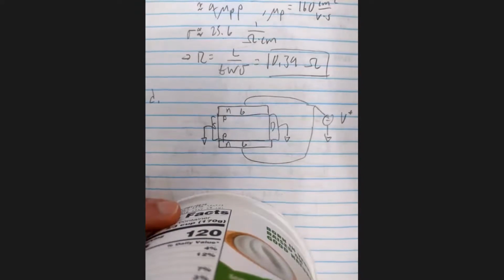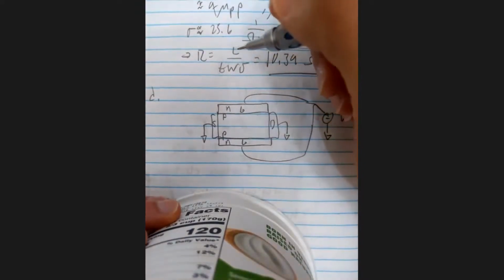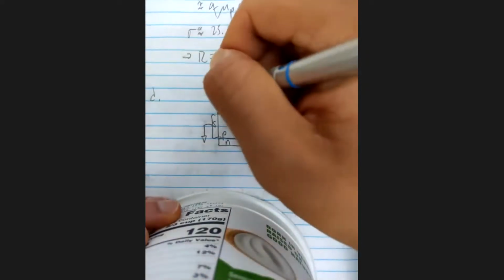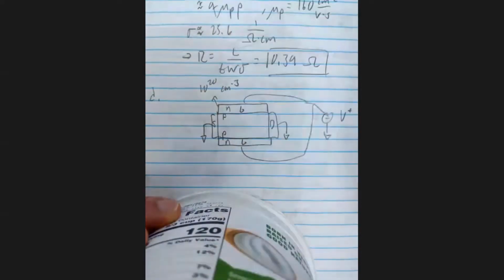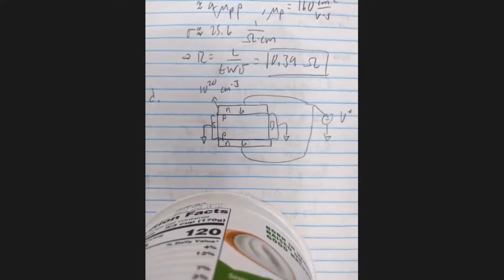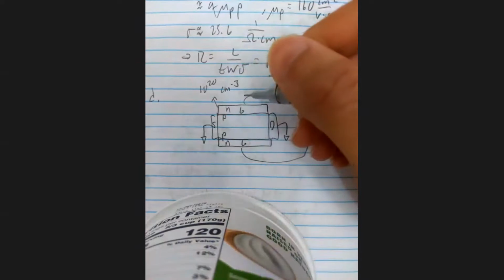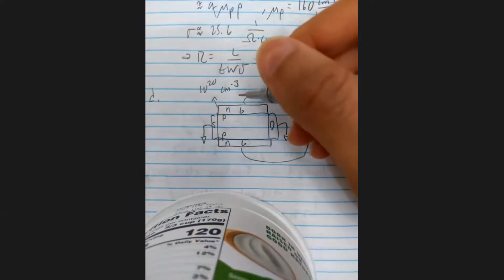So one bit of information that's useful from the first part of this problem is that these n gates are heavily doped to 10 to the 20th per centimeter cubed. That's 2 orders of magnitude greater than the p doping. So what we expect to happen is that, certainly these are p-n junctions, so they're going to have a depletion region on either side of the gate in the body. But because the body is so much more lightly doped than the gate, most of the depletion region will actually fall across the body.